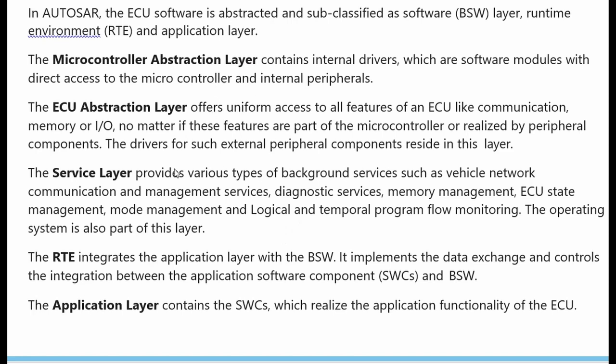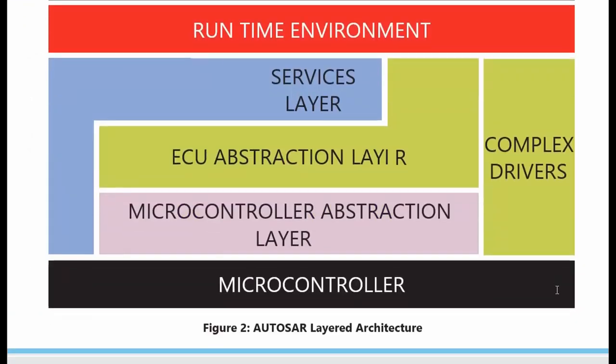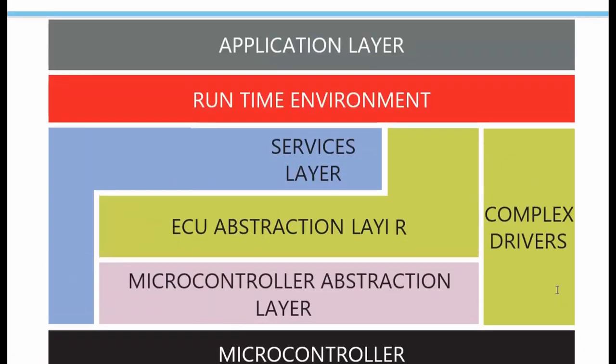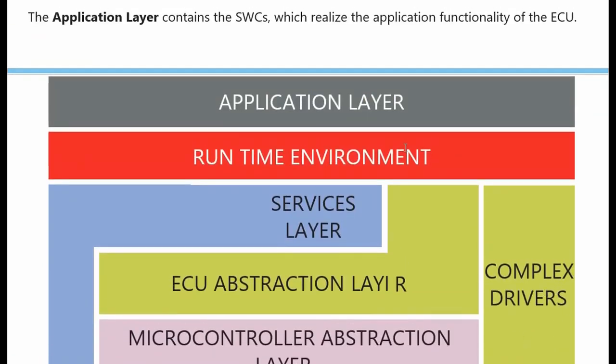The RTE integrates the application layer with the BSW. It implements the data exchange and controls the integration between the application software component and the basic software. Here you can see that you have application software, and here you have this basic software.